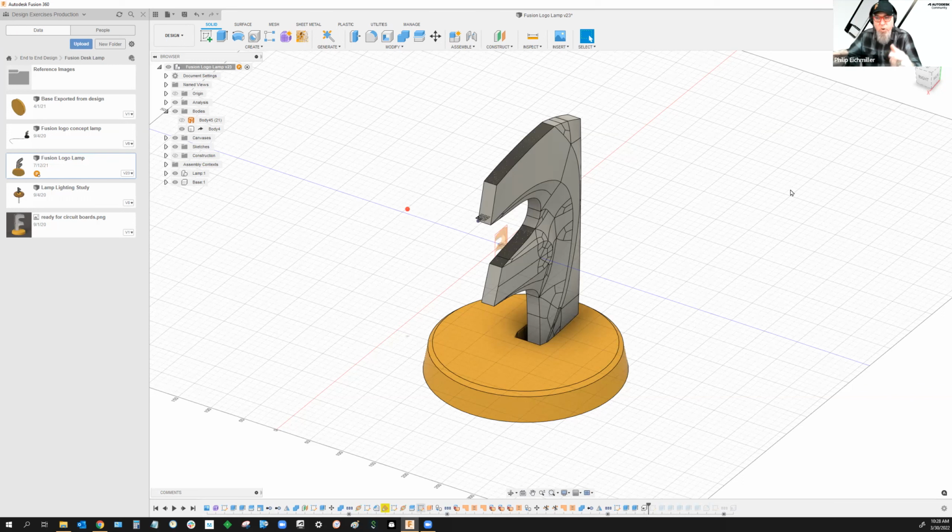The raw material for that machined casting is the casting. So in the bill of materials, it would say you take one of part A and make it A sub 1. Then if you add more finishing later, like paint it or mask areas off and paint it, it becomes perhaps another part number, or A sub 1.1 or something like that.